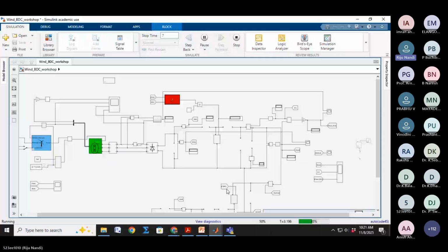Yes, small signal modeling is required, also for the circuit averaging technique. Can I share my opinion, madam? Yes, sir, you are right. But what happens when we are working with switching converters? All the switching converters are highly nonlinear. That is called switching nonlinearity, meaning periodically on, off, on, off. If we see their phase trajectory, we will get a limit cycle. Itself it looks like a linear system, but it's a non-linear system.